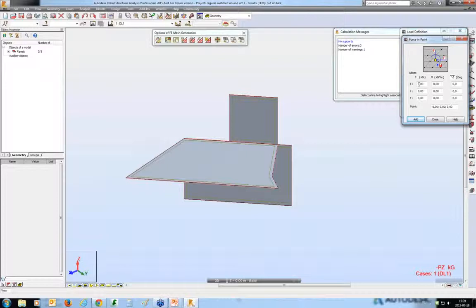And this has the shortcoming that when you redefine the mesh, you will need to do it again, selecting the newly generated nodes and applying the supports. Therefore, if you want to indicate the entire edge of the panel is supported, it is recommended to apply linear support to this edge. And then you just do not have to think about this definition again.